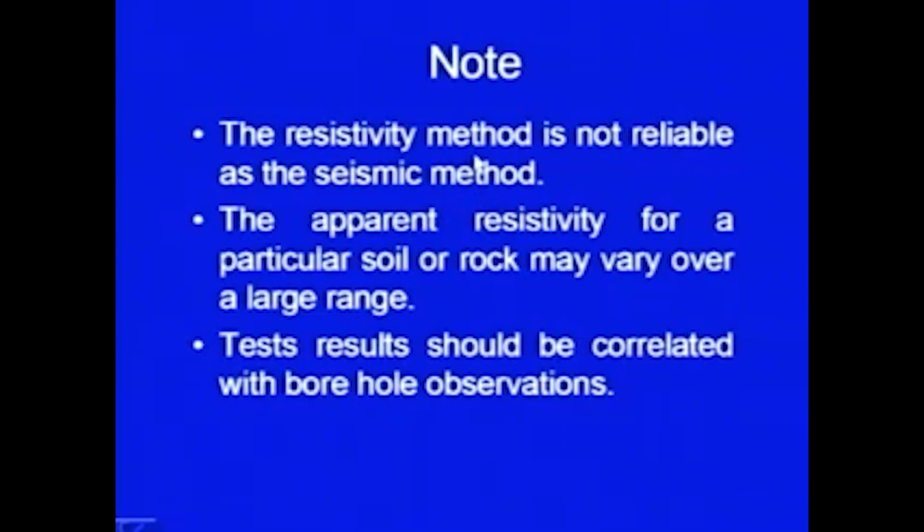Here I would like to put a note that the resistivity method is not a very reliable method. The apparent resistivity for a particular soil may vary over a large range, and therefore the test results should be correlated with some other tests, for example, borehole observations.